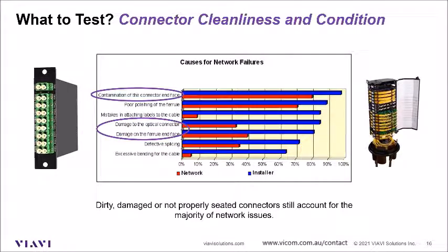And it might not happen straight away. You might have contamination that needs to be burnt in, depending as well on the laser power levels. It may take a little bit of time, and I've seen, for instance on the DWDM technologies, they use very high power lasers, and they literally burn through particles on the connectors, which then of course stops the network.